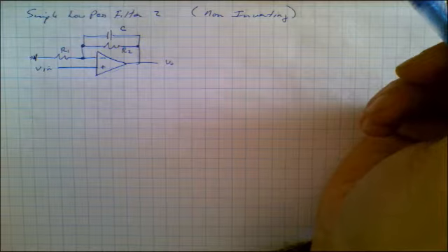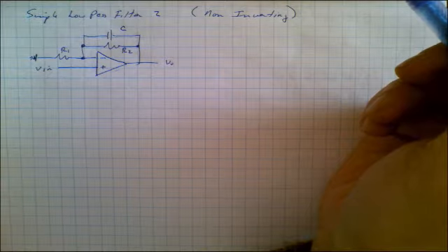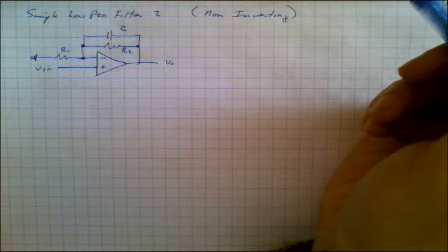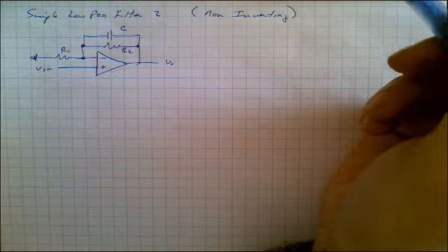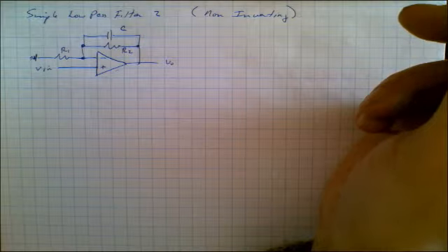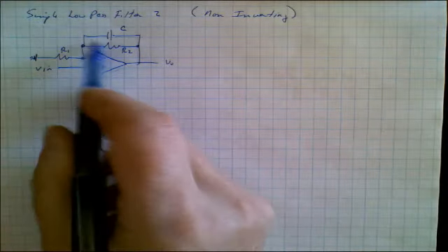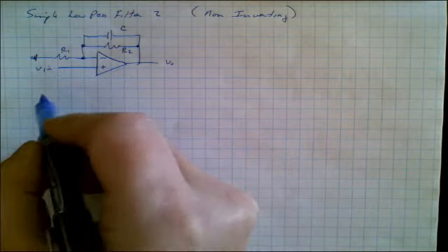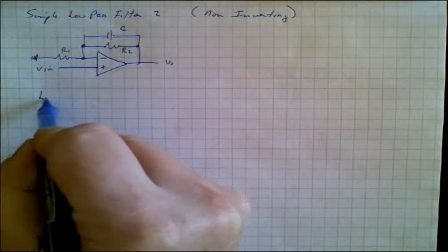We know that it has a range of gains as a function of frequency. And so we'd like to know, what gain does it start off at, and what gain does it end off at? Well, to find out, we could do a very simple analysis. And let's just say that there was no capacitor here. So we're going to find out what the low frequency gain is.